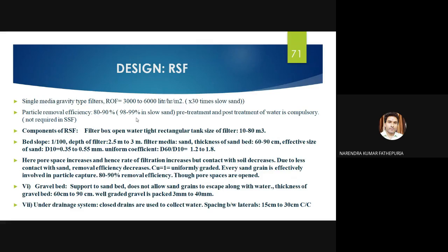For these things, pre-treatment and post-treatment of water is compulsory. Directly you cannot send water for the rapid sand filtration. Water has to come through various stages: aeration, pre-chlorination, and then sedimentation. Then it should come for the rapid sand filtration. Directly from the intake structure, we cannot treat the water in a rapid sand filtration.